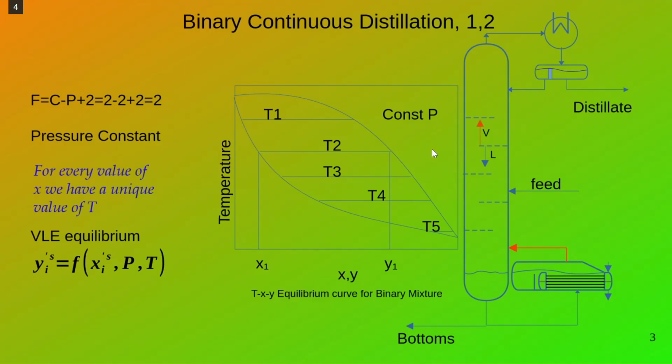Now, if there is any disturbance caused in the distillation column, the first effect it will have is on the concentration, which automatically means it will have an effect on the temperature of the trays. And if we read the temperature of the trays and they are not as per what it was designed for, it means that the column is not running properly and it has been disturbed.